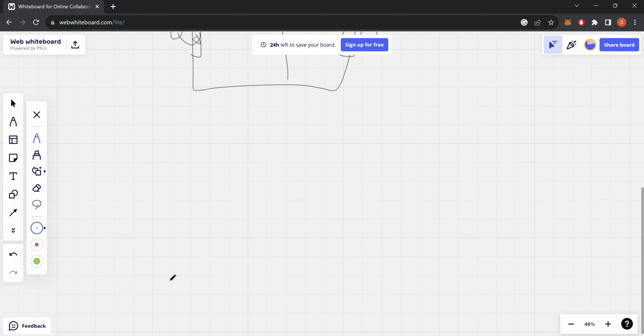I'm going to draw a profile view now. So this is like the wall, and there's this ductless unit up on the wall, and here's a person standing in the room, right? Happy person. So you get the idea what's going on. So up on the wall is this ductless unit, and outside is this little condenser. It's going to have lines that come in the wall. It goes up to here, and the return line is going to go back down and back out.